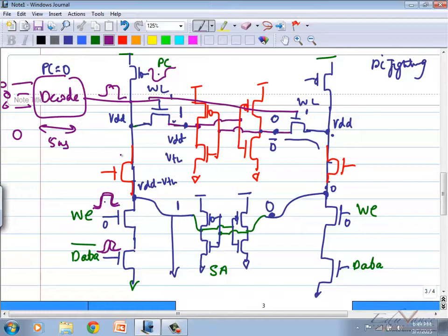Please. So first what we do is precharge, then write enable and data lines together, then one will flip in one direction, the other will flip in the opposite direction. What is a read operation? Precharge. Always first comes precharge, then word line and sense enable. That's it. Word line and sense enable, correct. Automatically the one that is 1 or 0 will pull it. Sense amplifier output. The output of your design that you will be checking is your sense amplifier output.